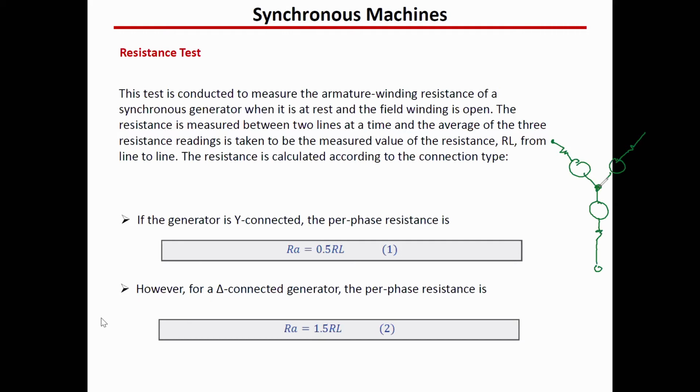So basically, what you're saying is there is no voltage induced in the synchronous machine. Yeah, there is no voltage induced because we are not running the machine, so we don't provide any speed. Because if we provide speed and field current, this is an AC circuit. We don't want this to be an AC circuit. We want it to be DC. So nothing here as an input for the machine. The machine is off. You just apply, as I mentioned, DC voltage. Okay. Thank you. Any other questions?